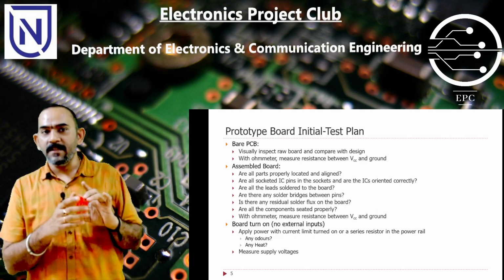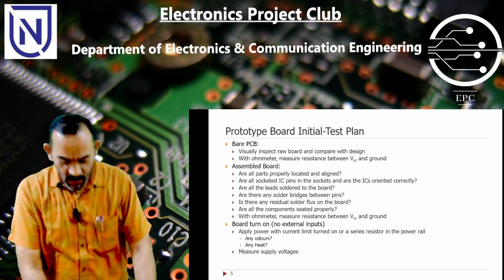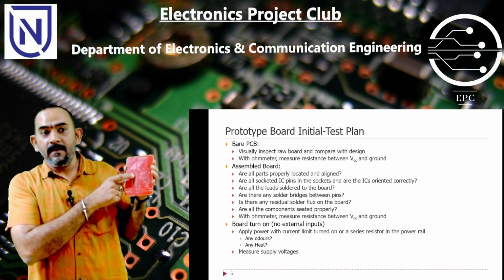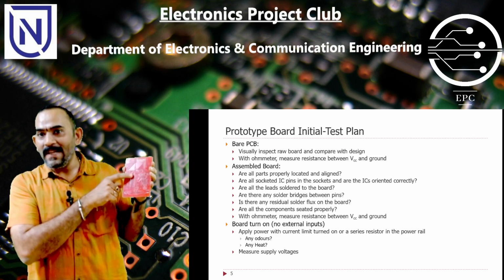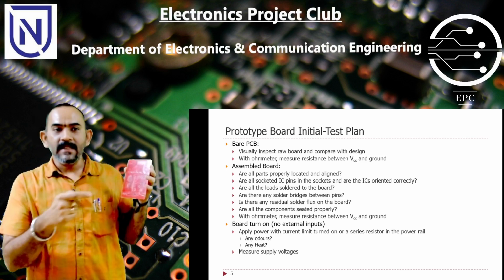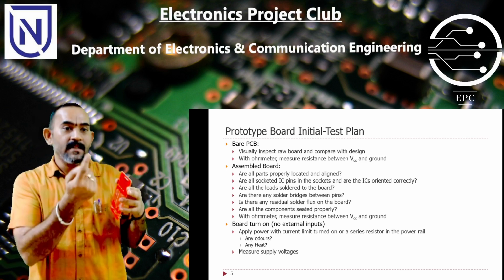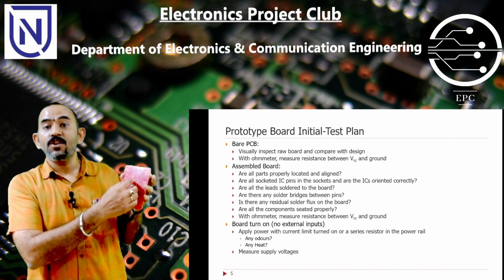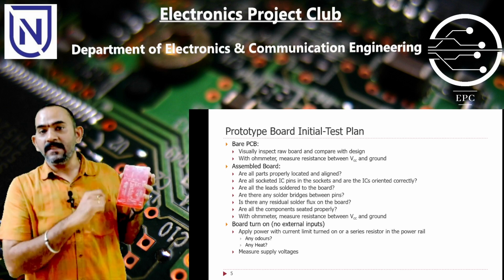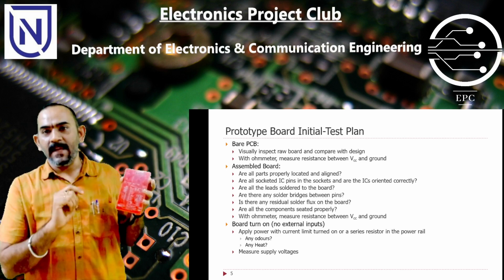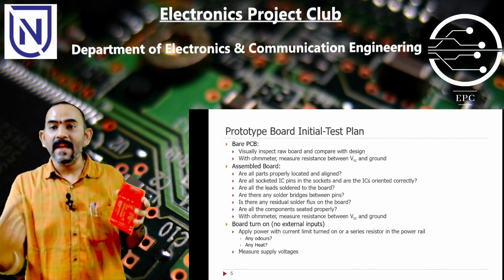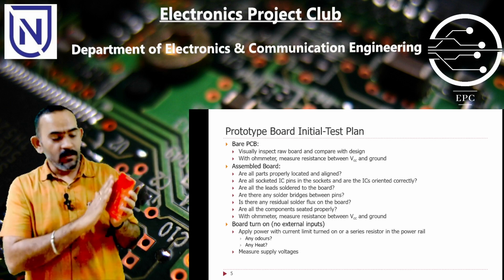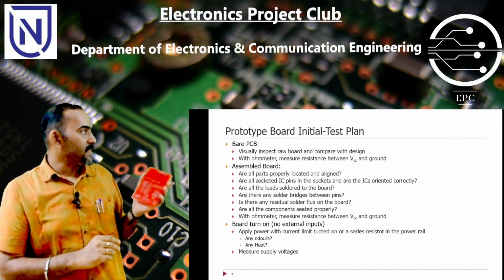When we say solder bridges, it is like when I solder on this board, two close-lying pins should not have been connected, but because I gave more solder here, they made contact and it caused a short on the board, which is bad again. Now you are creating a defect there, so we have to be careful and check for such errors.